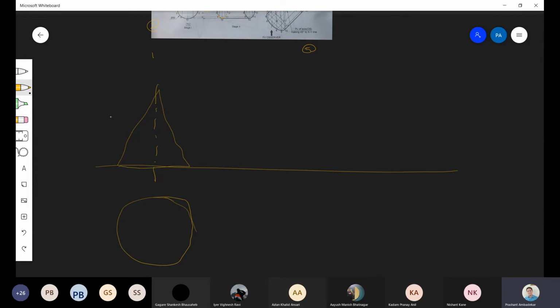So which is the axis? You can see this axis I have drawn here, the center line. Now this is making an angle of 30 degree with the HP. Means what will we do? We'll draw this axis here like this. What is the angle? Angle is 30 degree. Now on this we have to draw this triangle like this. Correct? Any doubt to any student?